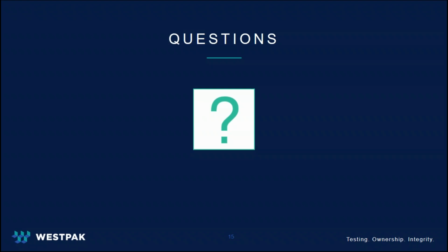Greg, we've got time for one more question. Can you talk about ASTM F88 compared to ASTM F1140? Which would be preferred? Any comments there? Most of our clients use ASTM F88. The 1140, if my memory serves me correctly, is the burst test. So I would say F88 is the preferred method for checking seal strength, because you're only taking a 1-inch wide sample and you get more consistent results with peel.